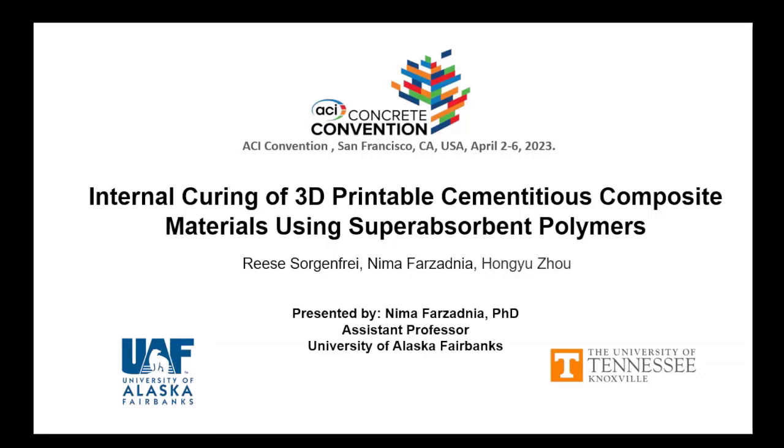so this is what I started when I was a research assistant professor at the University of Tennessee, and it is still in progress. Now a new PhD student is working on that. They're working with Dr. Zhou, who is already in the session too. So it's about internal curing of 3D printable cementitious composites using superabsorbent polymers. We did the feasibility study actually, and now more detailed research is going on.